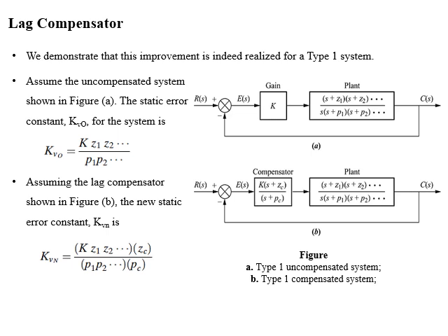Students, now we will demonstrate the improvement in steady state error for a system of type 1. If you look at figure A, we have a type 1 system and we have to improve its steady state error. Its static error velocity constant will be given by Kv0 and will be equal to the product of gains multiplied by zeros location divided by poles.